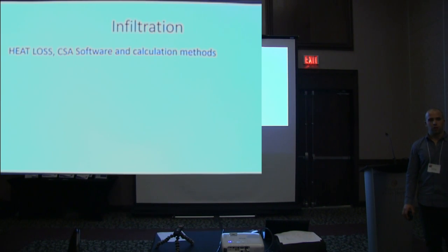Is it an hour or is it a day? It's not an hour and it's not a day. It's in the middle. It depends. A thorough takeoff of the whole set of drawings, call that an hour to write down everything you've got, and then maybe 2-3 hours to input everything and make sure you're correct. So a total of 4 hours maximum, I think. You're talking about a 3,500 square foot house.